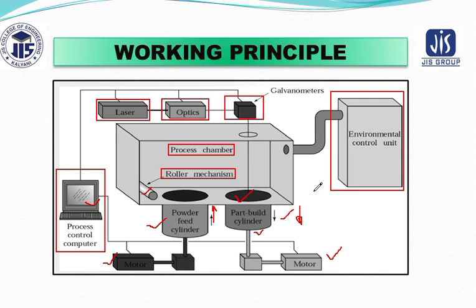Next, a laser beam guided by a process control computer, using instructions that have already been generated from the 3D CAD, is used. As I already told in the first lecture of rapid prototyping, we have already mentioned the generation of the 3D program of the desired part. The beam is then focused on the layer, tracing and sintering a particular cross section into a solid mass.